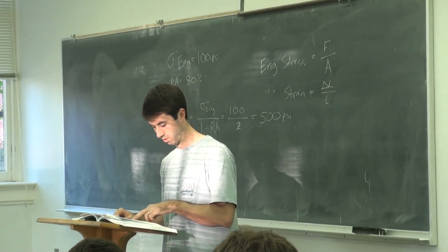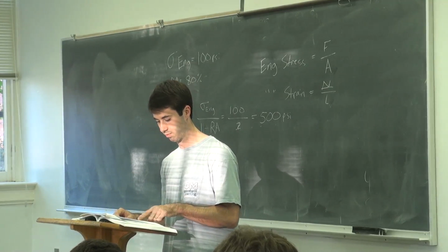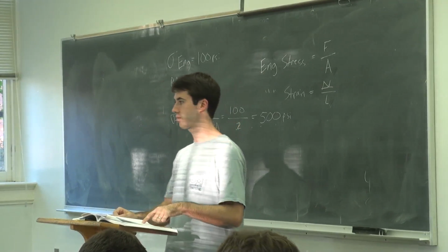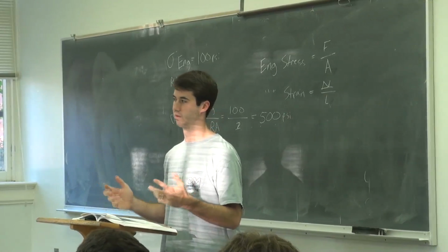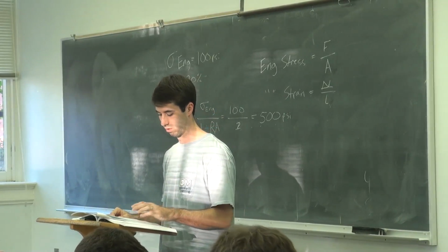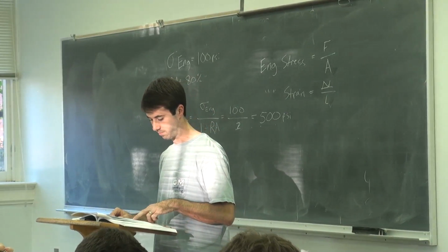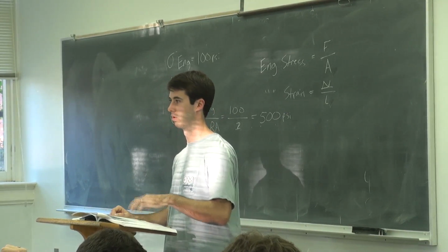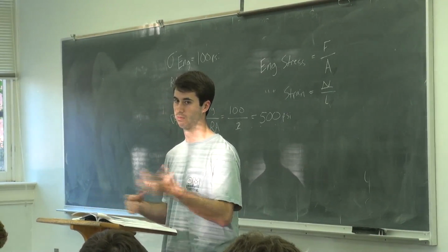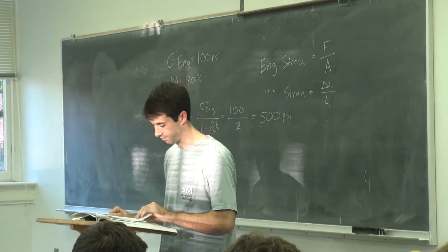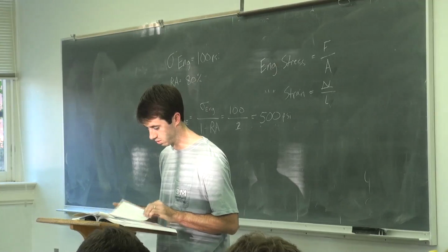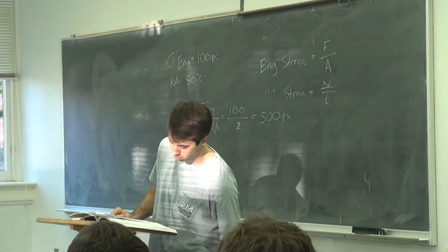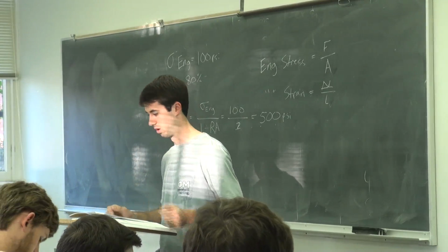And then you've got these other random little segments. Then you got the log of MR down at the bottom. That wasn't in the original 72 guide either, that was something to account for climate stuff. So basically, if you just cut out the ZR, S0, and the MR terms, you're back to the 72 guide. If you add them back in, you're up to what they do currently. Just so you can distinguish between the two. On the next page, we'll just run through a quick analysis problem with this.